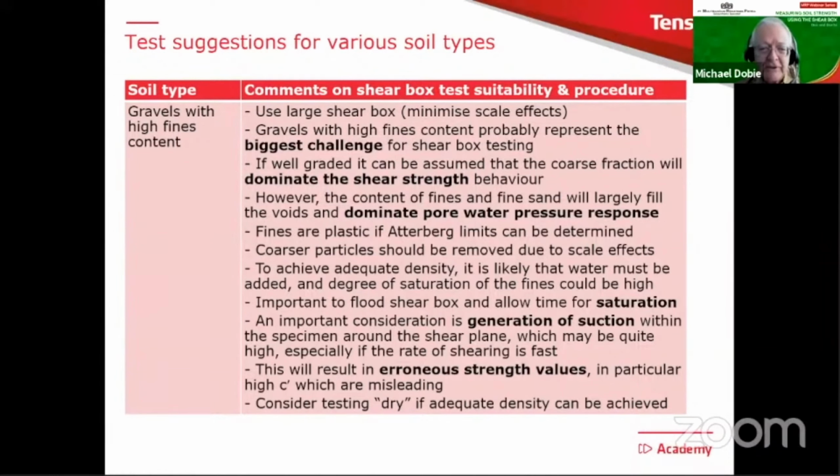Well, I think these soils are difficult. But one possibility, if you're satisfied that the coarse particles will dominate the shear strength behavior, is to actually do the test dry. You might have to remove some of the fines, otherwise it would go hard, it would kind of set inside the voids, but you could test them dry. It's a possibility, but it's a judgment you have to make when you're testing this kind of soil.